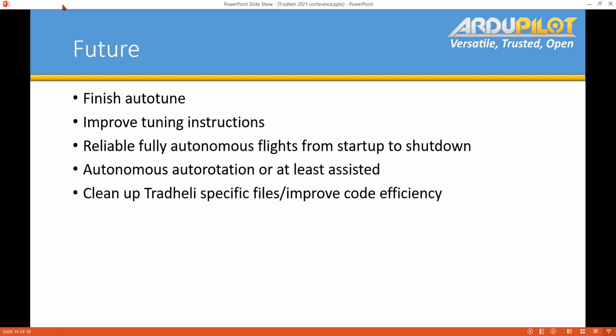And I was looking at that setup thinking they probably had a roll mode on their mounting system that was probably getting down towards the order of about 15 hertz. What's the impact of that on the roll tune? I guess it would just show up like a regressive mode, and it would take it into account if they ended up with the oscillation mounting system.